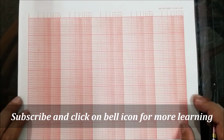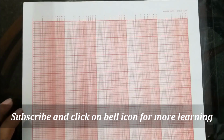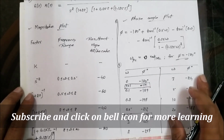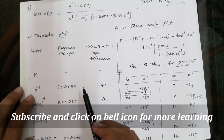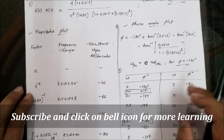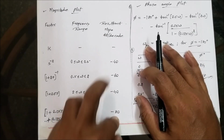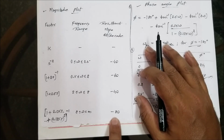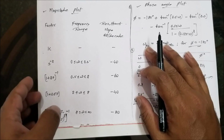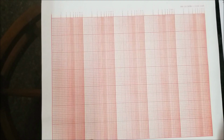Now moving ahead to step number 4, wherein I want to plot the Bode attenuation curve. So this is the problem we had, correct? For this problem we have already determined the magnitude plot, that is the resultant slope table, as well as the phase angle plot table, correct? Now if you carefully observe, the maximum slope that I require is minus 80 decibels per decade. Minus 80 decibels per decade is the maximum slope I require to plot the Bode attenuation curve.